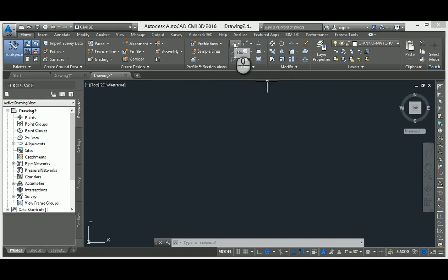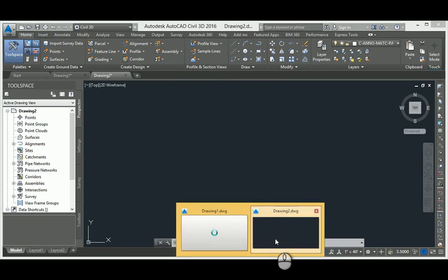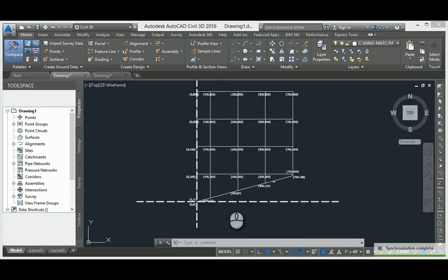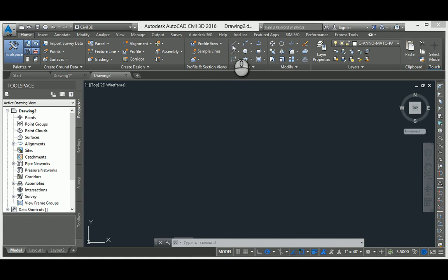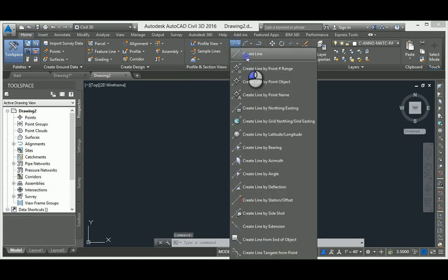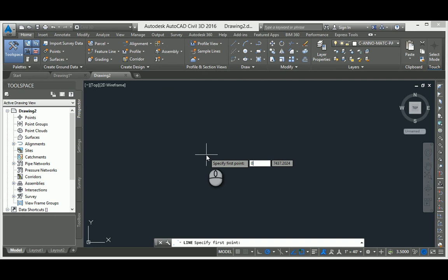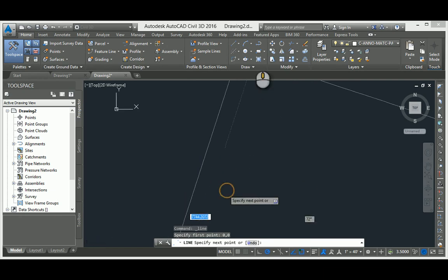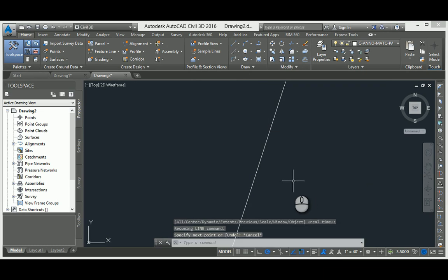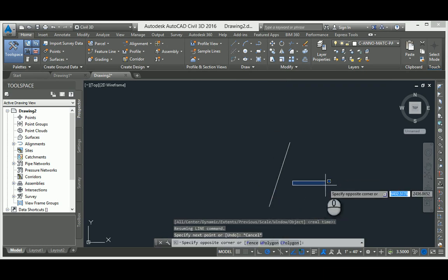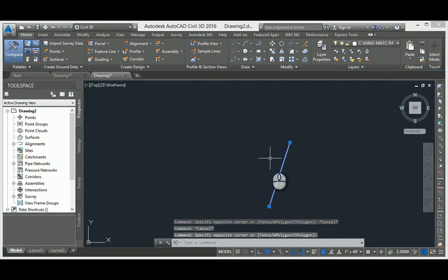So the first thing we're going to do is create the outline. It looks like this. So let's go to our blank file, go to line, and we're going to create a line, and we're going to start it at 0, 0. Enter. You can see that I'm off the page, so I'm just going to set this down, hit zoom fit. Now I can find my 0 point. It's down here at the bottom. 0, 0 is down here, so let's just delete this and start over.